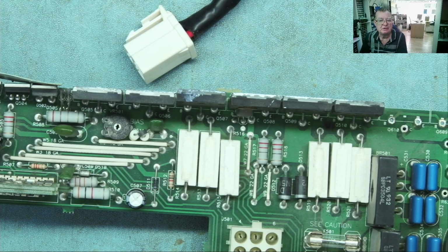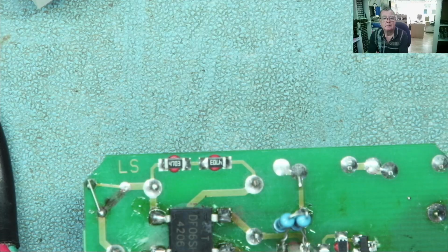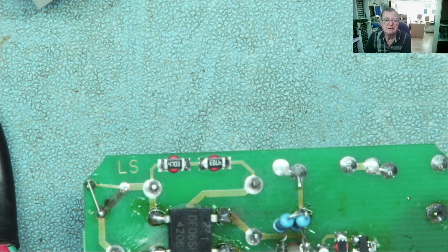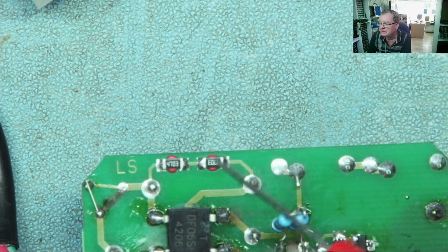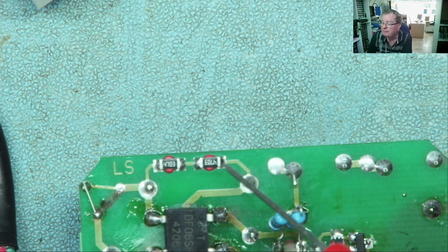High value resistors are a slightly different thing. They don't tend to burn up when something else fails because, well, they're high value, so they can't pass much current. But they do have a habit of just wearing out, just failing. And there's two very common places we will find this. One is in switch mode power supplies, and you will find resistors like these. So again, this is not 4703, it's 470 and 3 more zeros.